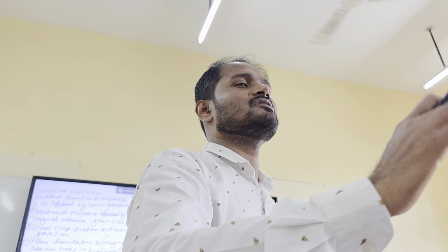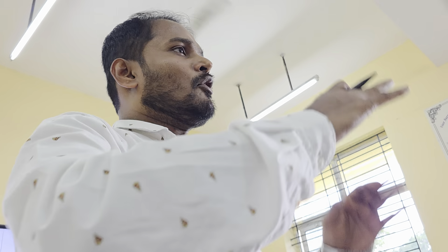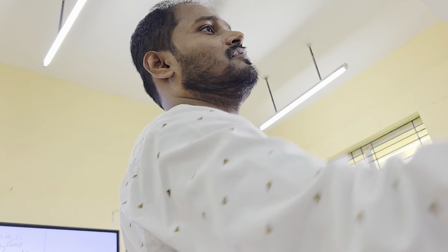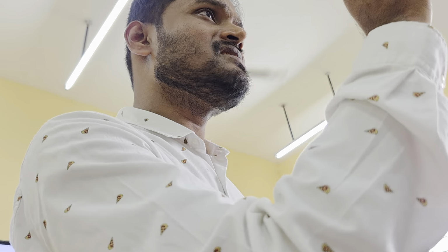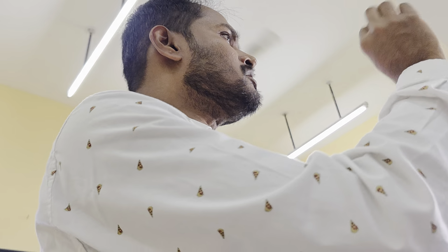So during this process, with time, impurities will be reduced. But still you are providing oxygen. So a time will come when the concentration of oxygen will increase in the molten steel, which is not good when you do casting, because the next stage is casting, so that you can do rolling, hot rolling or cold rolling. You have visited the industry, you know, right? The moment you do casting, casting defects will come out. Blowholes, surface blows, porosities, pinhole porosity, you will know this. Some defects will come. That is not good actually.